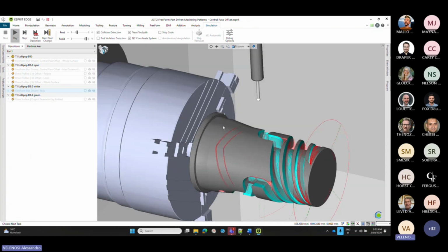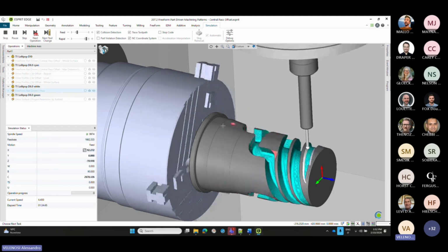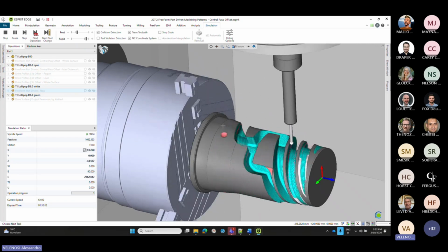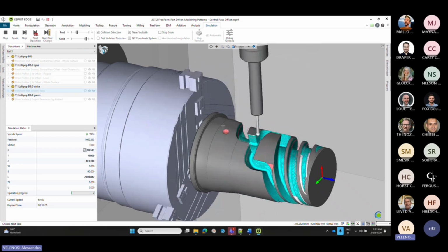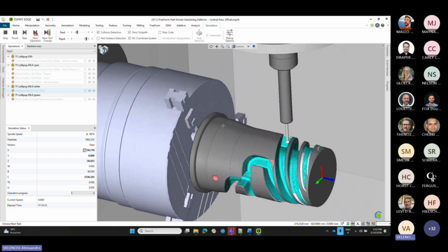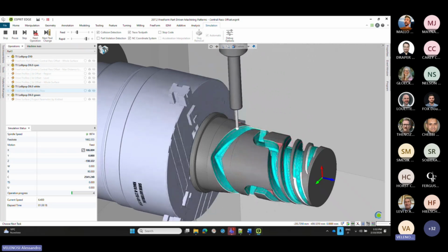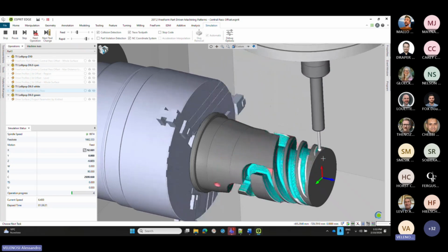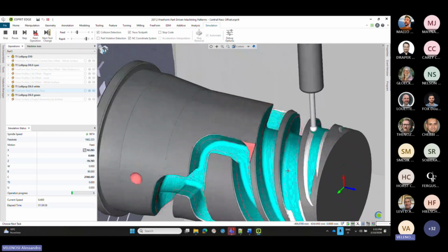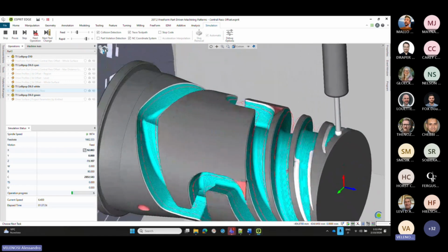And we can observe that this kind of toolpath was not producible by the knitted surface, because in this case we have not, let's say, a basic topology offered by the knitted modeling commands, so the four border or the closed. Here we have a groove which has multiple branches, so there is not, let's say, a basic topology able to produce this kind of machining pattern without any interruption.